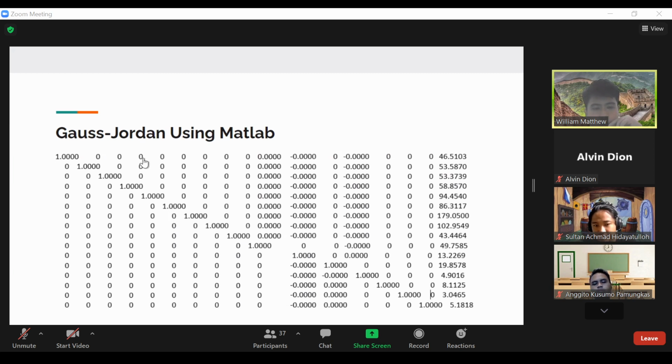So when the iteration runs, the value will be detected as infinite or too small. Then the value cannot be displayed by MATLAB using Gauss-Seidel. So we tried to find another method using Gauss-Jordan, where the value of the temperature can be found using the identity matrix. So the diagonal values of the matrix will be set to 1.